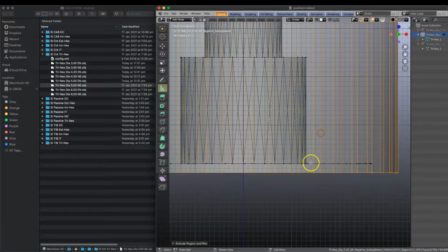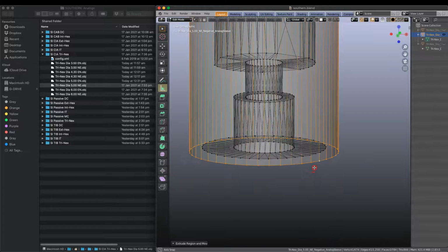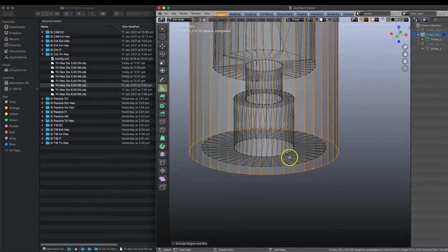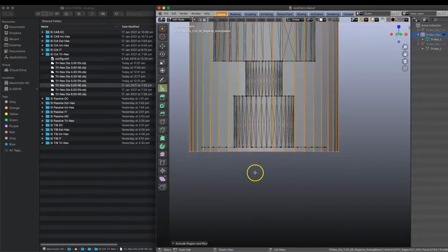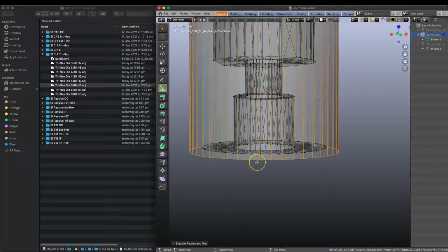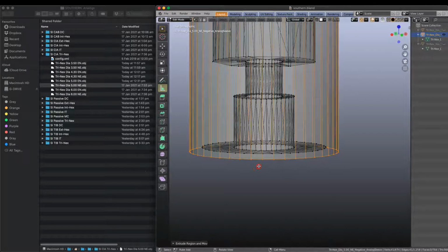We're going to zoom in again. What we want to do here is keep the plateau, but create a little thin small ledge. Remember, this component will be designed to be extruded through the dental model, both on the upper side and the lower side. If you've got IPD implants, they have a screw entering laterally across to fasten the analog, so we want to make sure these will create perfect cutting tools for us.